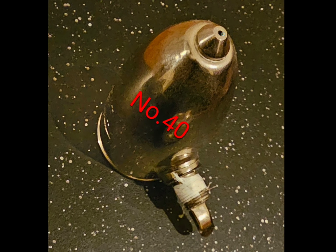Take a look at the opening. This is the outlet, all right? How big do you think that outlet is? What, maybe a millimeter? 1.5 millimeters? No more than 2, I guarantee. The reason why you can never get that thermostatic float to go in the lock position is you don't have the outlet capacity. Now, some might say, but look at the inlet. You have an 1/8 inch inlet capacity. That should be more than enough to get this to blow up. Well, it doesn't really matter how big the openings are down here. If all you have is a 1.5 millimeter diameter outlet, you're never going to be able to generate that wind capacity.